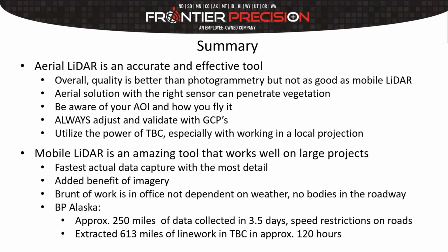And then the mobile LiDAR stuff, obviously, it's not a secret that it really blew us away. It worked really well. It was fast, it was accurate, probably not a feasible solution to use on 1,600 feet of road or even a mile of road. Might be overkill, but definitely in those longer projects, it really shines. You get the added benefit of imagery, and the brunt of the work is in the office, so it's not dependent on the weather. You don't have to have people in the roadway.